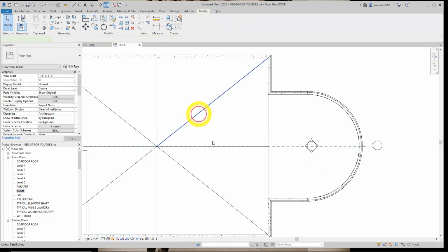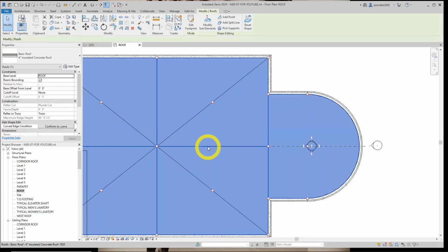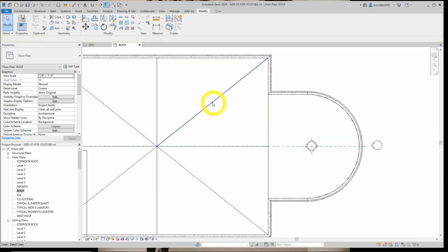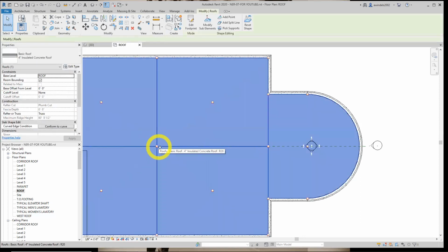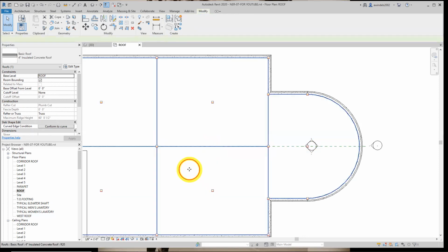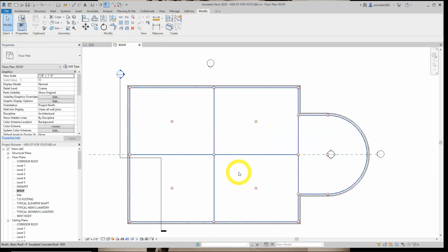I got my points, so we can see when I hover somewhere on this roof. Now this roof is selectable by clicking at split areas. I can select it with the face here, or I can select any one of its little features. These temporary lines, not so much. I want to delete those. That's this next step. They're no longer needed. And that would also select the roof if I select its split line as well as its face at this point. So just know that.